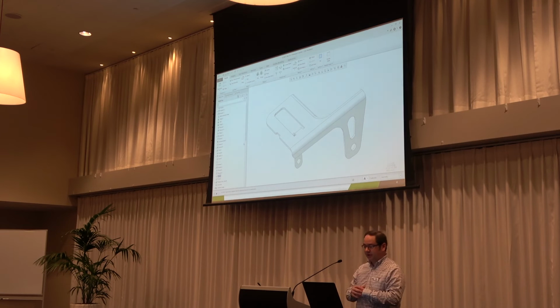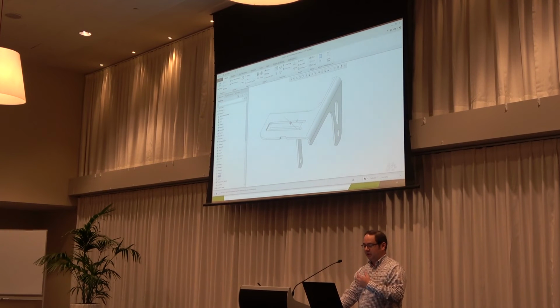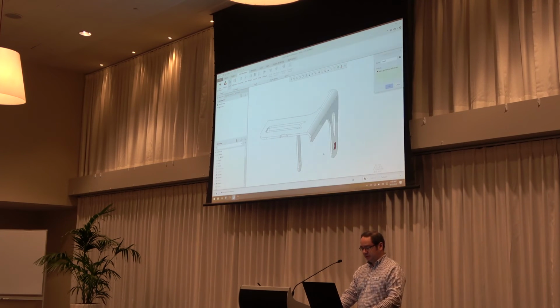So here I am inside Creo. I've got a sheet metal bracket here that I'm designing, and I want to start looking at, well, what should I be doing in this design phase, okay? So we've just got a new live simulation tab up here to start that process off, okay? So I'm now running Discovery Live. So there's three things I need: material, loads, and constraints, okay? I've already got my material defined. I can see it up here in my materials tree. So I'll put some constraints on there, just fix the surfaces.